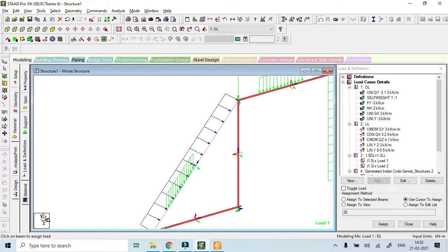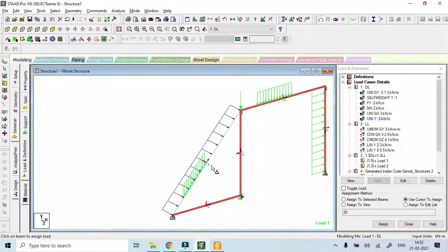Global axis is based upon this corresponding coordinate which is shown here, and is common to the entire structure as such. But for beams, depending upon the orientation of the beam, either in 2D space or 3D space, here I have shown 2D space. Whether it is in 2D space or 3D space, each corresponding member has got its own local axis.